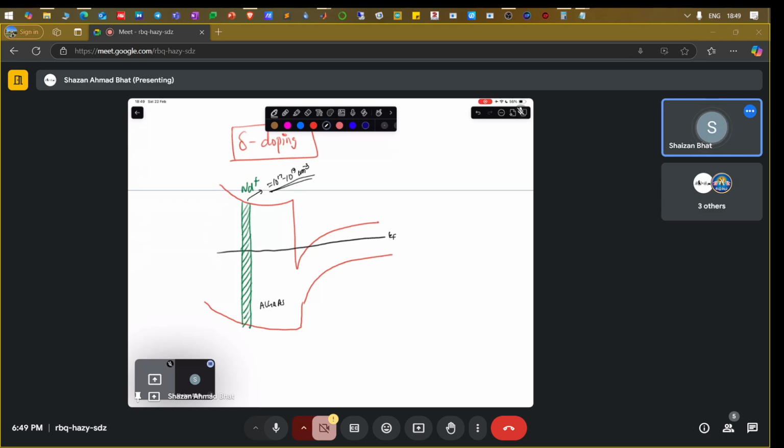From your basic device physics course, let's say you have a p-n junction. Let me draw it. You have p on this side and n on this side, you have positive ions, negative ions, and a depletion region. Whenever you draw the charge profile of this, let me call this center the metallurgical junction. You have a positive charge here and a negative charge here.